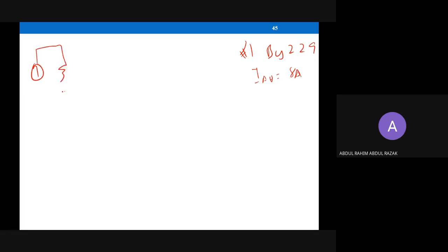So there will be this kind of diagram. You have the junction temperature and the ambient, and here will be R theta JA. This is your PD. And what we discussed inside the pre-recorded slide, using the generic formula, would be TJ equals PD times R thermal JA plus TA.